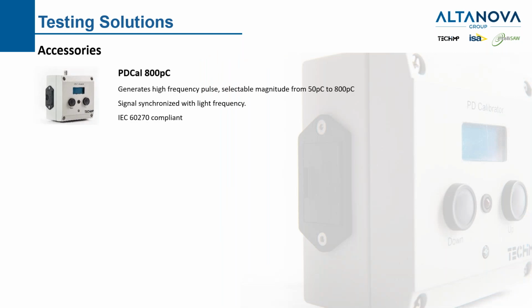Accessories. For rotating machines, I've identified mainly 3 accessories that can be useful for the customer. The 800 picocoulomb PD calibrator that generates a well-known charge PD signal. It's IEC 60270 compliant. Can be used for a sensitivity test to check that everything is going on correctly from the sensor up to the acquisition unit.